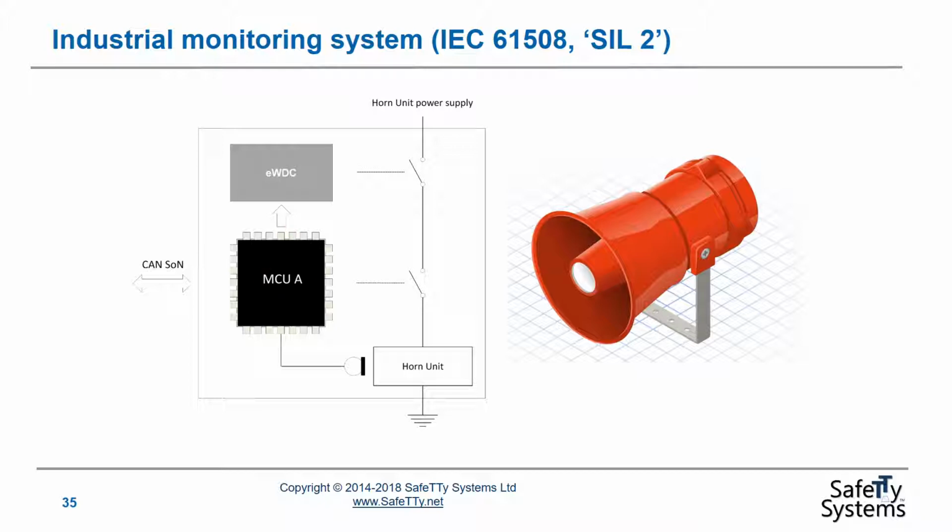That would be an important consideration in this type of design, because false alarms coming from one or more of the sounder units in an industrial facility would be likely to reduce the faith that the people in the facility have in the alarm system, and it could mean the next time there is a real alarm, they ignore it, and there are bad consequences from that.